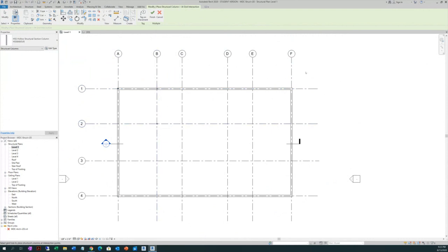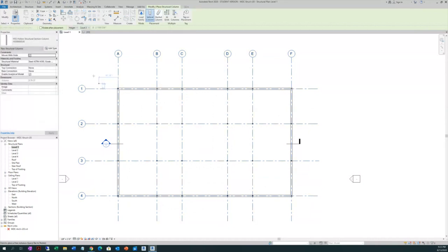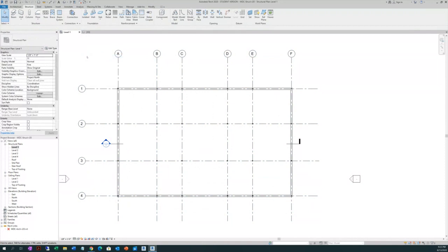Then you come here for a kind of crossing selection. You click from the upper right side, click over there, and go the opposite way. Then you see those columns are there from level 1 to level 2. Then you finish mode here. Cancel because it's active, and that's it.